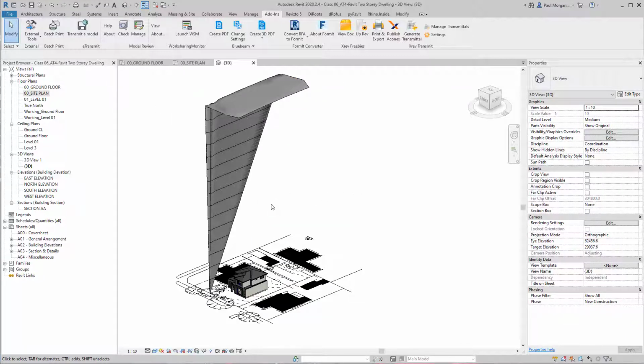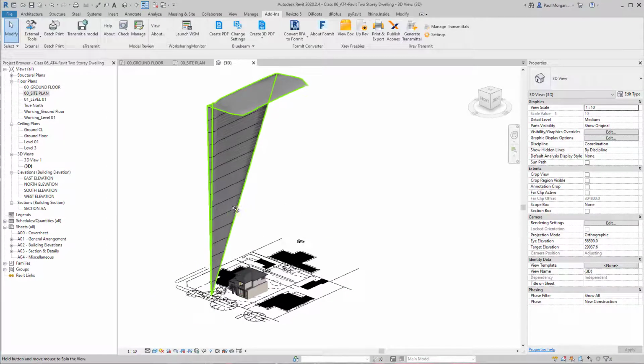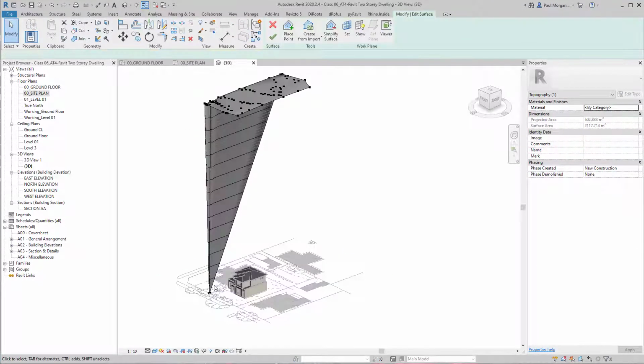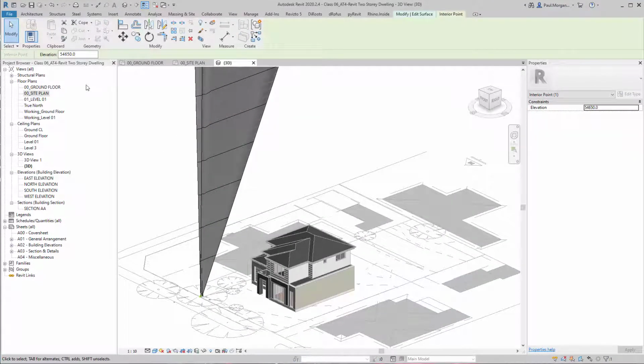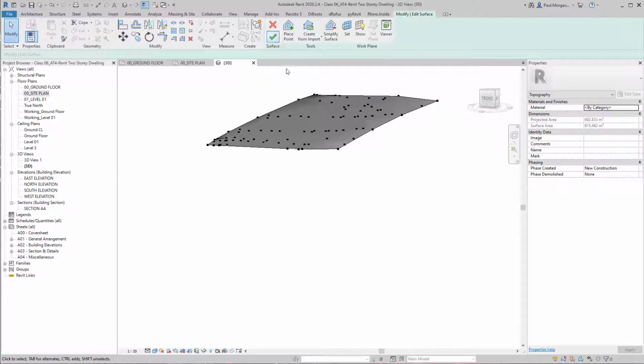So I fixed up all the points, but you'll notice there's one that still looks like this. I just want to give you guys some reference because this may happen to you. All this is that there is still one more point down here that I need to fix up, and that one is sitting just at 131. Oh, there was another one. That one's at 131.2. There we go. And now our site has moved up here. That looks all nice and clean.